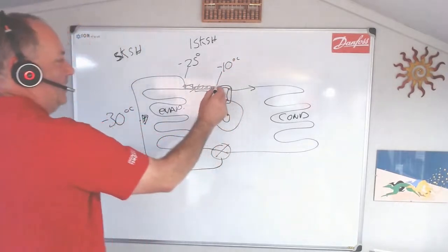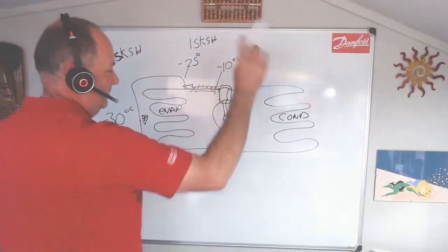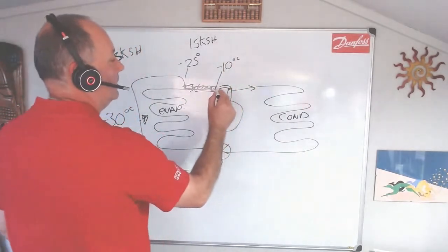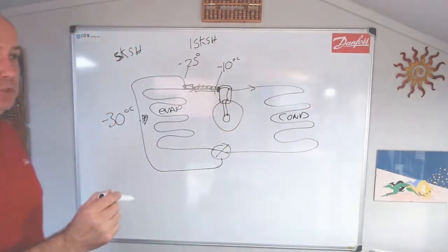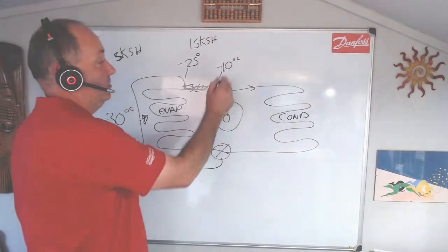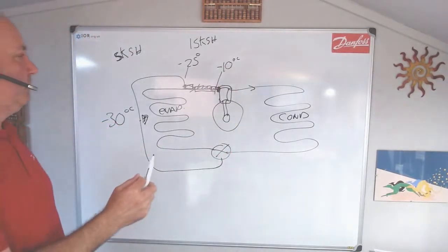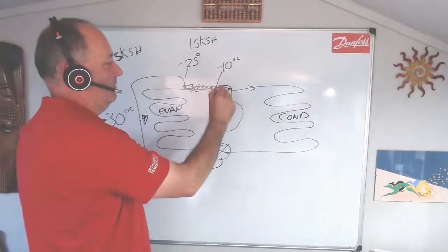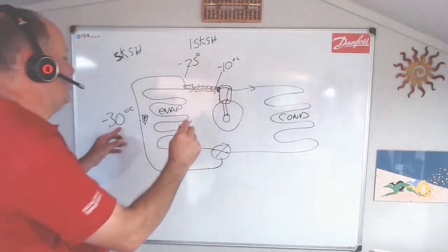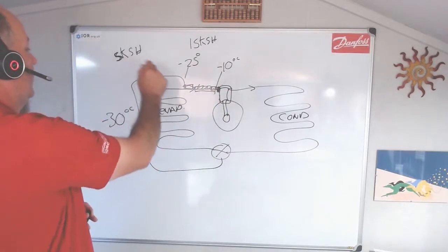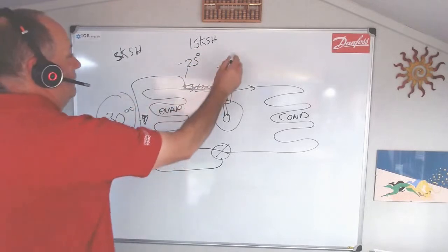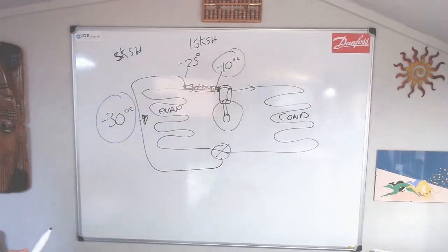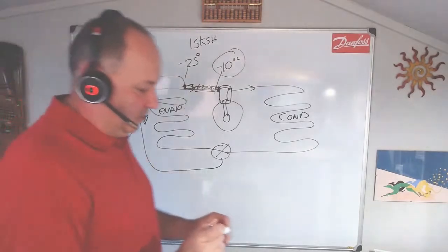So if we're minus 10 there, and it's a nice, moist ambient temperature, we're going to have frost on our suction stub. Doesn't necessarily mean we've got liquid, just means that it's cold. But you only know if it's cold and not liquid by actually measuring your superheat in your evaporator and your suction superheat, or your total superheat, which is that. So that's the way to check if your machine or your system is behaving itself.